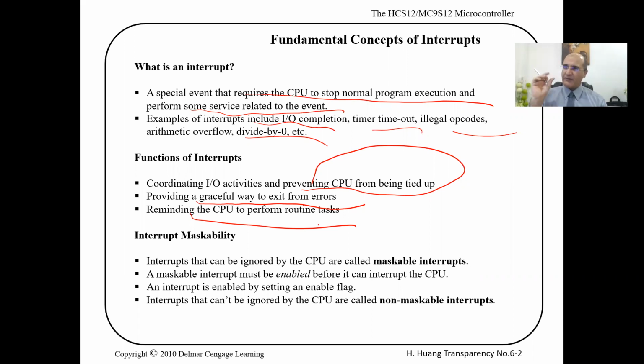I want this thing to happen every second. Well, okay, then what do I do in between? Well, go to sleep. And this is a really critical and important thing in battery-powered systems. And today we're talking about the Internet of Things, right? The things at the end of the day are what? They are computers, controllers, processors running, battery-powered usually, and doing something specific.